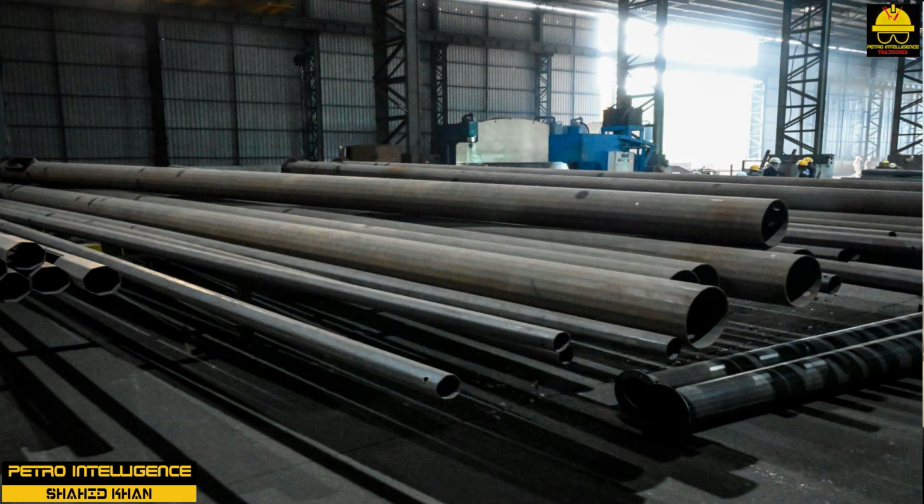The steel used for equipment is low in carbon, 0.3% or less, sulfur, and phosphorus, and contains sufficient manganese to offset the effect of sulfur. It may also contain small quantities of silicon or aluminum. The low carbon content promotes ductility and weldability.